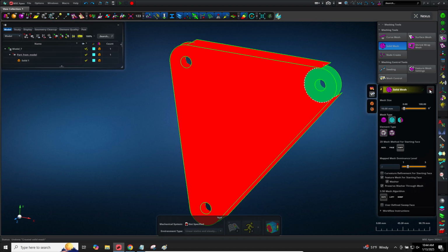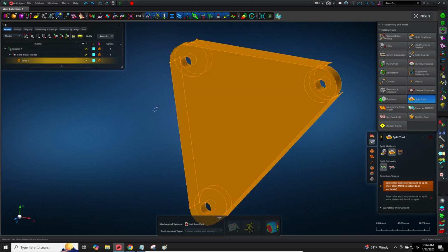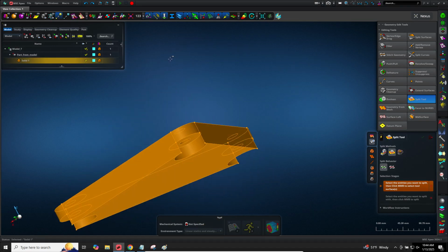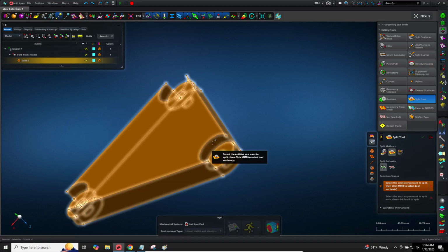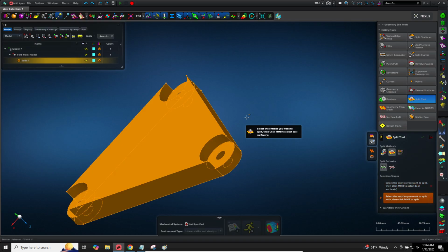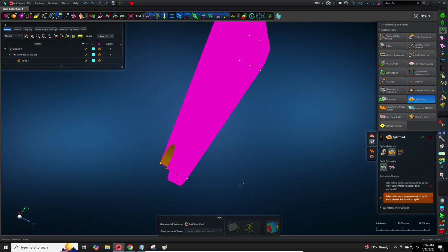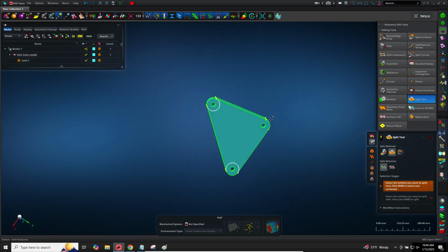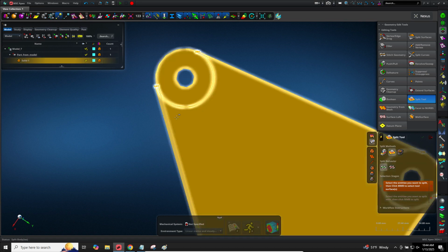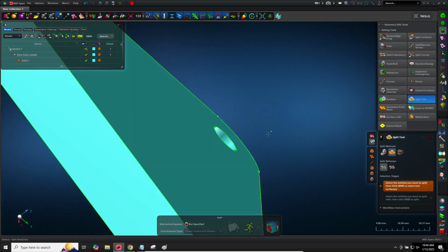But now let's do this for the other regions of the model. Let's split or partition the geometry. So let's select this big geometry. And let's select maybe this face. Or first, let's click the scroll wheel so it turns magenta. And let's select that face and click the scroll wheel again. And now I get a second partition, if you will, and you can see that it's in dotted white lines. Let's do this for this other region.